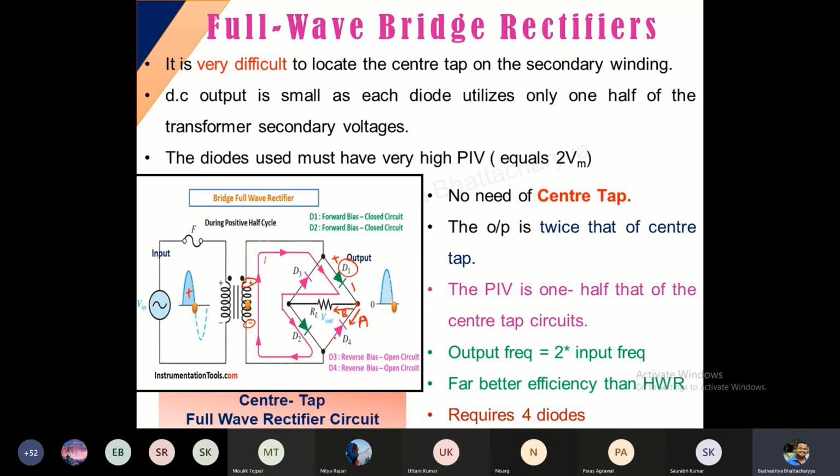So nothing will flow through D4. The question that I just now solved, I told you that this kind of arrangement we can observe. So through D4, there is no current. Whereas this B current, at this node, can go either in this direction or come in this direction. But the direction towards this green diode, you can see this is positive, positive minus. So both D1 and D2, it is actually a path which is shown over here, like this zigzag path. So at this point, we are getting an output based on what the input was.